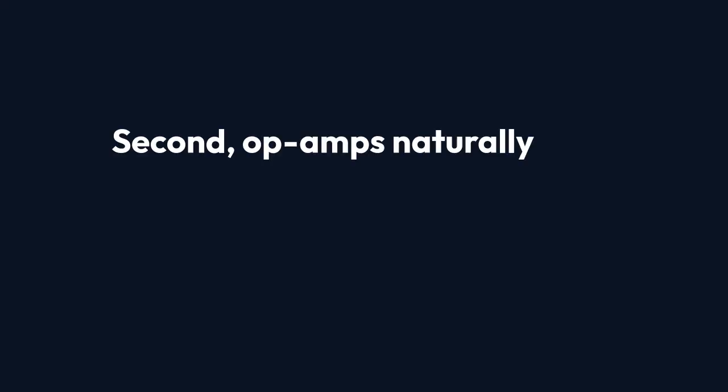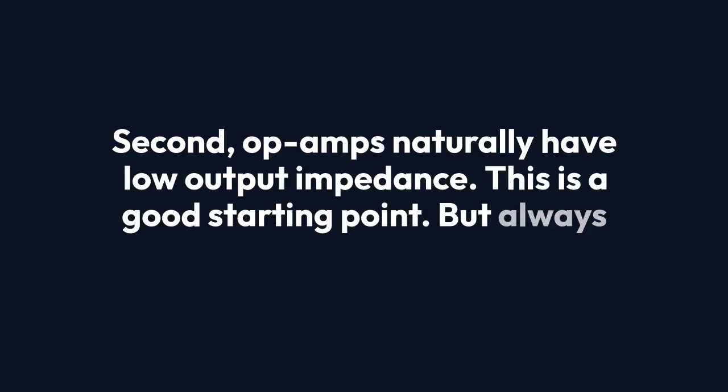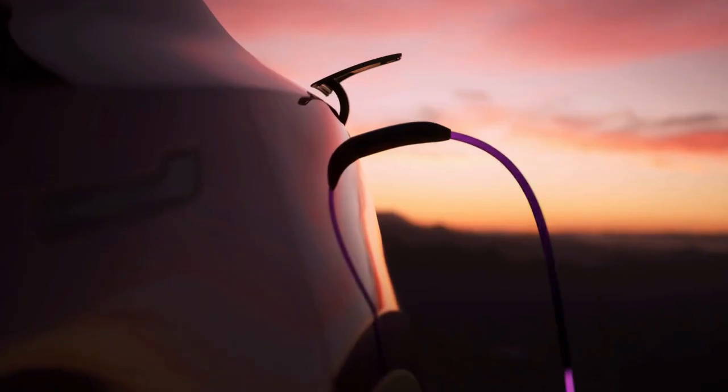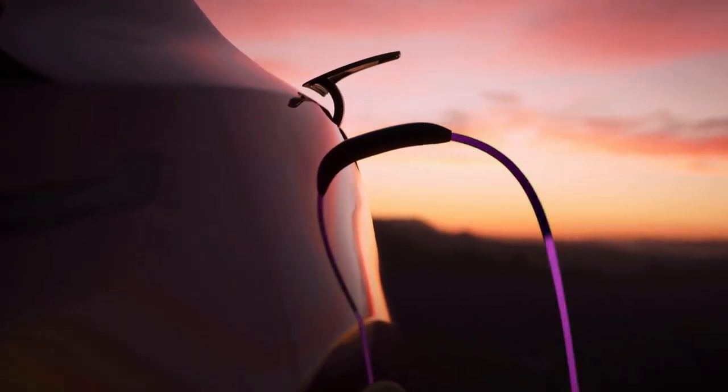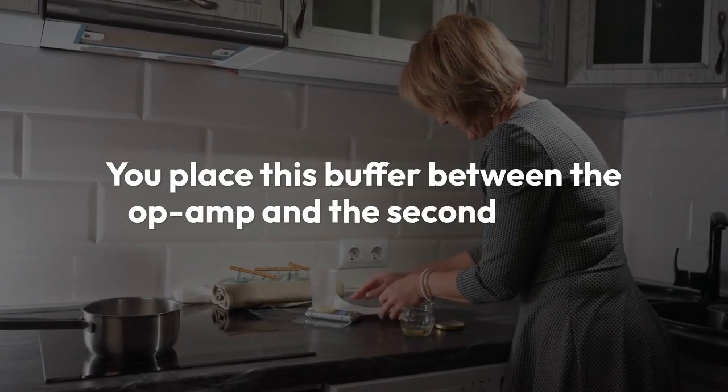Second, op-amps naturally have low output impedance. This is a good starting point. But always check the datasheet. Third, sometimes, a simple voltage follower or buffer stage is needed. You place this buffer between the op-amp and the second stage.